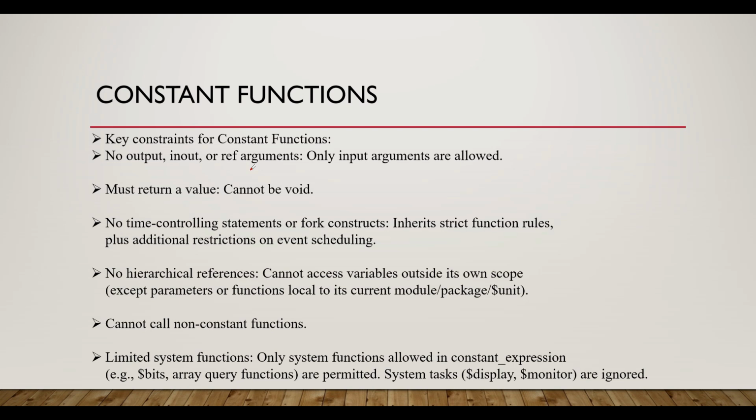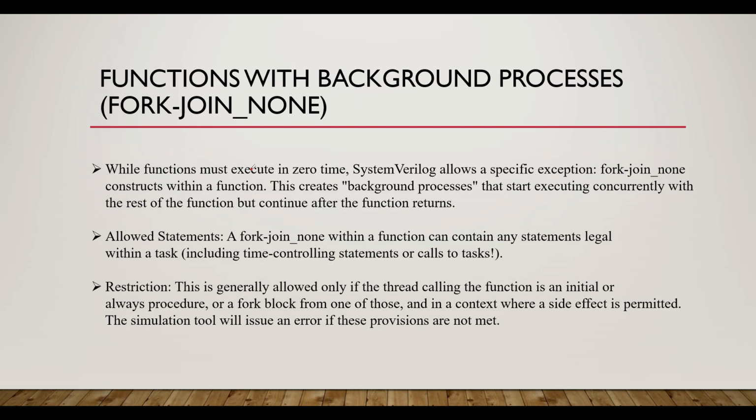System tasks like $display and $monitor are ignored in your constant function. Now let's see the function with a background process, that is fork join none. We will also discuss fork join none later, but for now, I am giving you some insight about it.